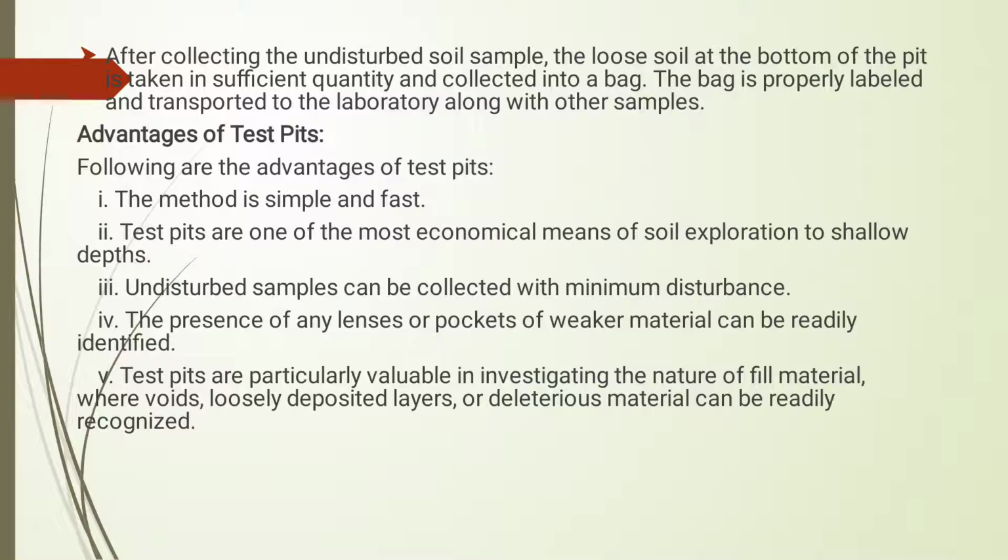The main advantage of the test pit method is that it is simple and fast, and it is the most economical method of soil exploration to a shallow depth. Here, undisturbed samples are collected with minimum disturbance. So, the test pits are particularly valuable in investigating the nature of fill material, where there are voids, loosely deposited layers, etc.